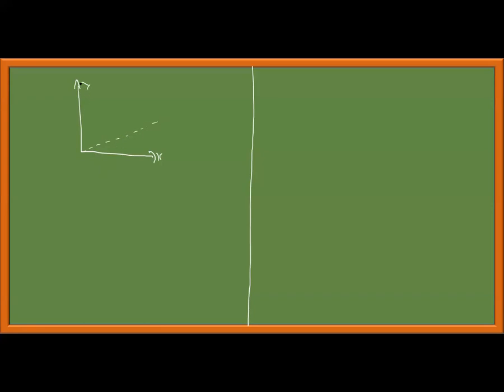If this is my plane, there's a plane like this, and this normal is in the x direction. There's one more plane I want to find the transformation for. This is at an angle. This plane is also given by its normal. In 3D, it can be like this. This is a plane which is perpendicular to this. This is the normal. This is the tangential. For this plane, which is at some angle theta, I want to find the state of stress. Okay, let me write neatly.